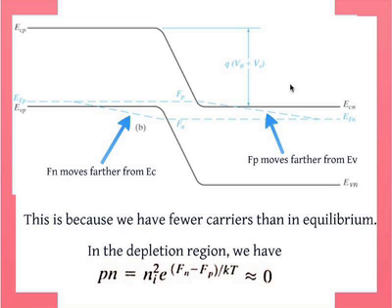On the other side, the opposite happens. Far away, it's still the equilibrium. But now, it's the n-type, the holes have been extracted across. So the quasi-Fermi level for the holes has to go away from the valence band. So it goes up. Okay? So you see a splitting up and then they meet in the middle. And this difference between the quasi-Fermi levels right here is the applied voltage, the reverse bias voltage. Okay? And of course, it makes sense because you have a carrier extraction, right?